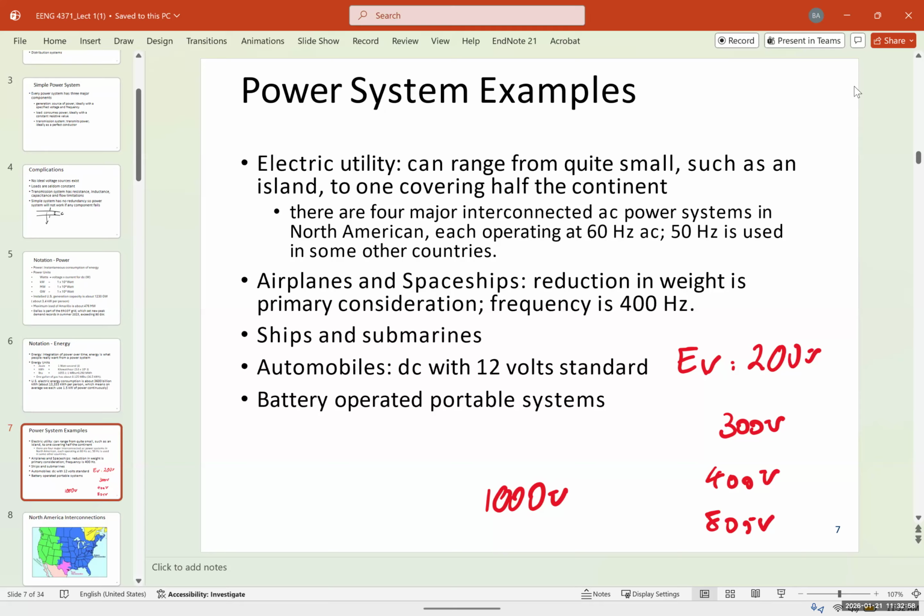A normal one is around 20 kilowatts, because AM transmits from one side of the world: the radio frequency hits the stratosphere, it's reflected like a mirror, and you can get it on the other side of the world. That's the reason you can receive an AM station that is in London. FM is around 20 miles; the curvature of the Earth limits it. With AM, you have to have very high power to send that signal.